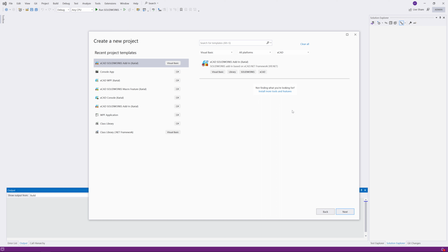A macro feature is an advanced mechanism in the SOLIDWORKS API, allowing developers to create their own SOLIDWORKS feature, which will be very similar to the standard features of SOLIDWORKS. Those features can produce geometry, expose dimensions, can have property manager pages while adding or editing, can have preview, and much more. Let's say we want to create a custom feature to create cylindrical geometry in SOLIDWORKS.